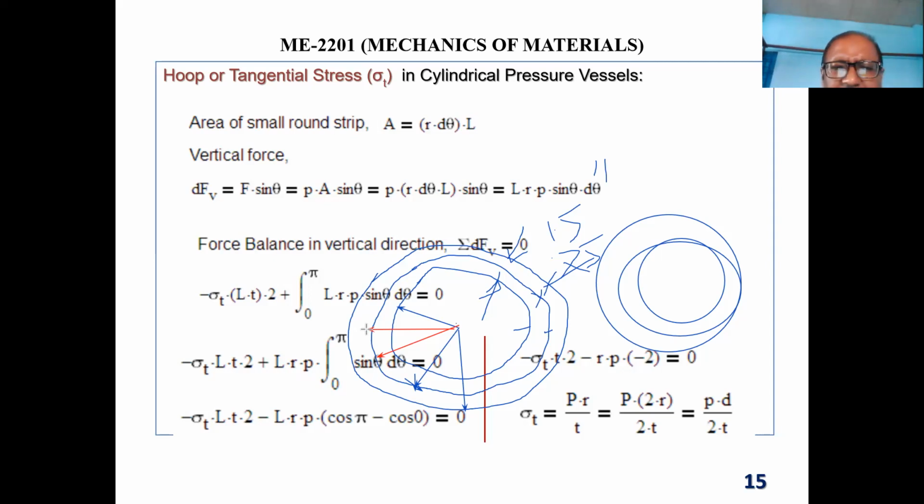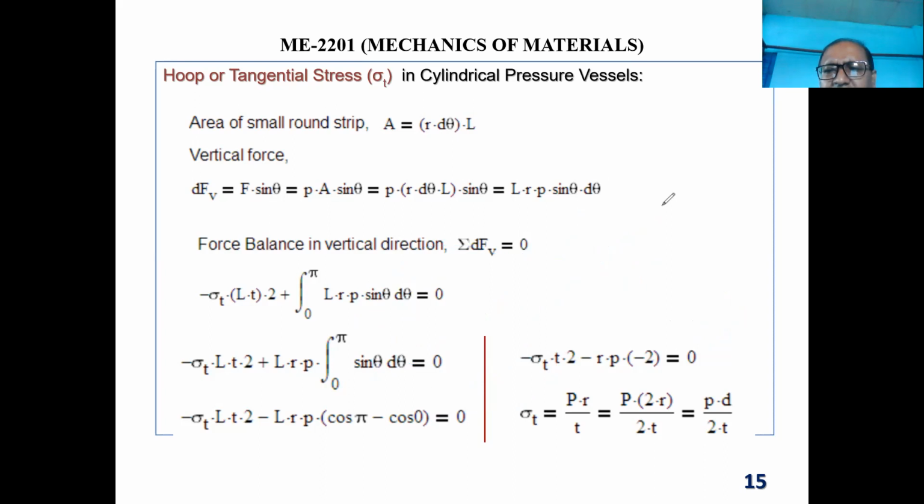But if you pressurize, then what will happen? There will be slip of the material. This cylinder might be slip at the common surface because there is no interference. There is just loose pipe, loose fitting. For example, a smaller pipe, you just put inside of a bigger pipe, and then it's pressurized. If there is no interference, then it will move along this direction.